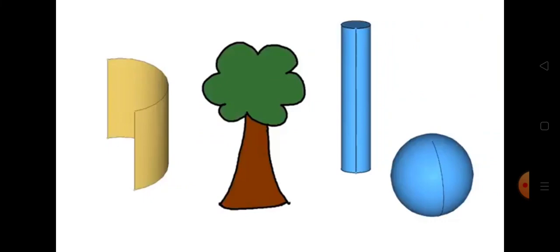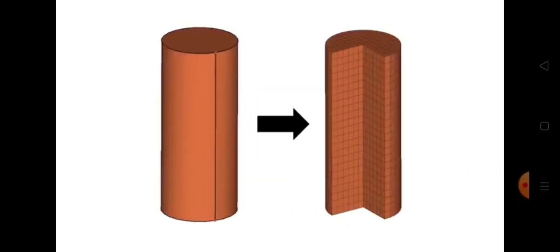You need to find that out first, and you need to mesh the elements. That is just discretization. Even before going into the concept deeper, you first need to know what discretization is. It is nothing but breaking a bigger component into smaller components. You see in this image, there is a cylindrical structure, and I made that into smaller boxes, which are smaller elements.